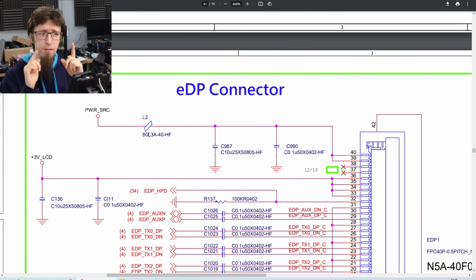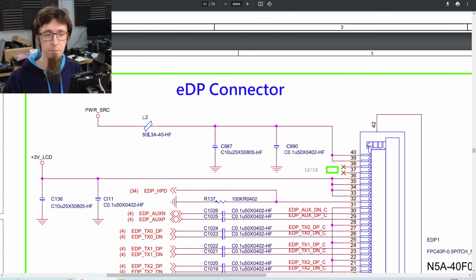But this is a very small inductor. It's tiny. It's actually more known as a ferrite bead, and it's not really doing this job. What this guy is doing is acting as a high-frequency filter. So again, like a normal inductor, it resists changes in current, but it's doing this for only high-frequency stuff.